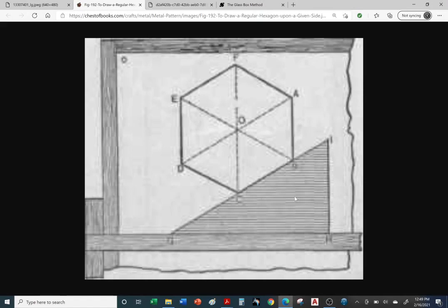So this is at a 30 degree angle. Then you would flip the triangle to draw this line. Okay, let's go back to this line. So you line up your T-square with the edge of the table. Line up your triangle with the T-square. Draw your line. And then you can slide it up to draw this line, to draw that line, draw this line.